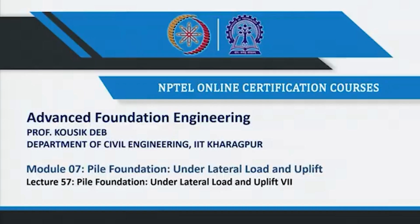So, last class I discussed how we can model the pile as a finite beam, and then determine the deflection, slope, bending moment and shear force at different depths along the pile, and we assumed that the horizontal modulus of subgrade reaction is uniform along the depth of the pile.